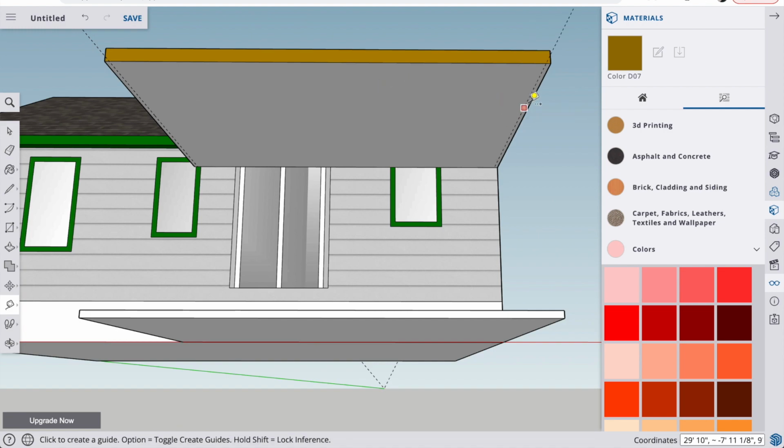To create the individual beams, I'm going to again go back to the measuring tape tool and make a lot of guidelines across the bottom face of this roof. So I'm roughing these in. I know a 2x4 is not really 2 inches, but I'm going to go over 2 inches and 16 inches to get an idea of how it would look.